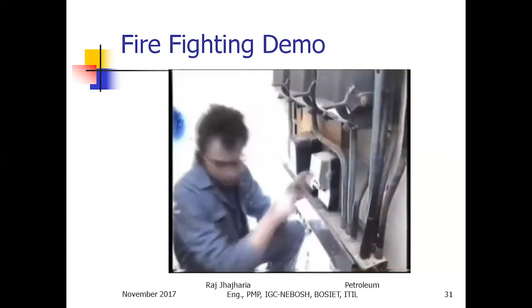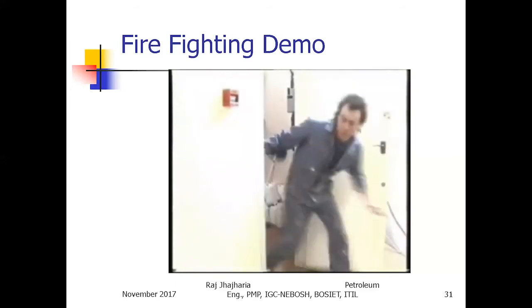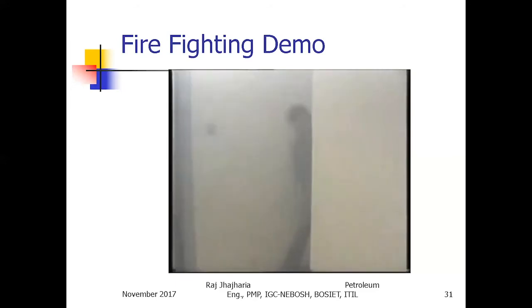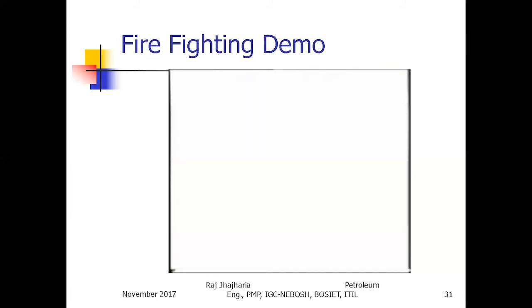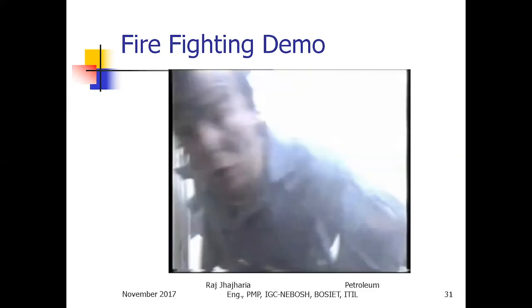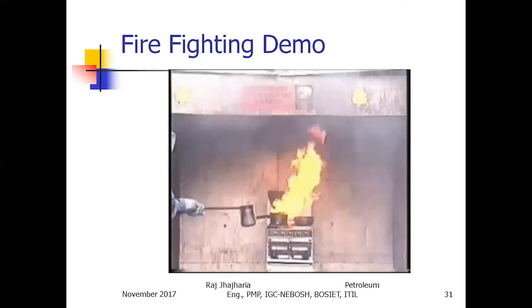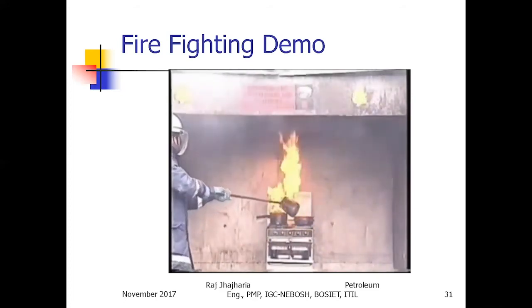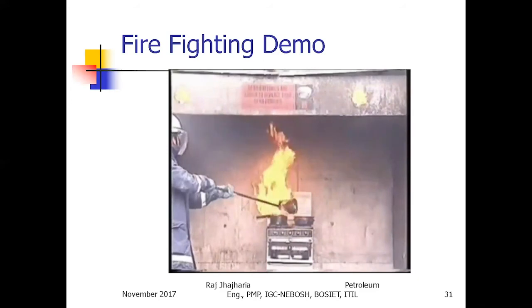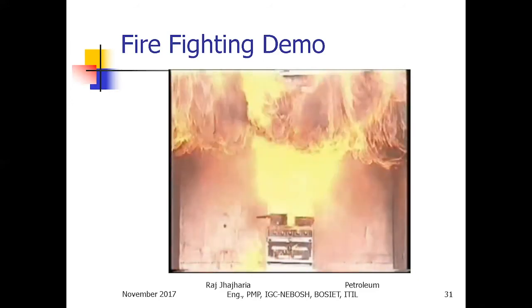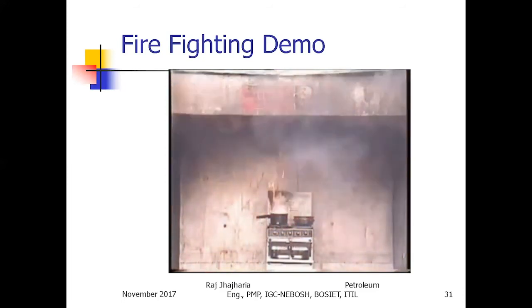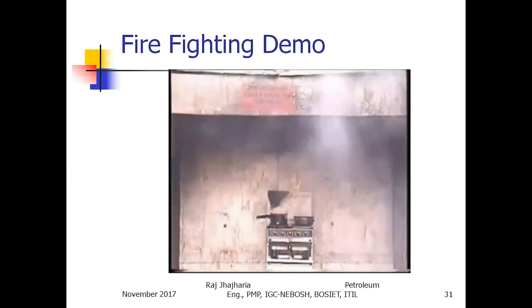There are some fires in which water must never be used, because it'll either make the fire worse or it's potentially lethal. Most people are aware that water and electricity do not mix. The likely outcome of applying water on anything electrical is electrocution. And the reaction you will get by adding just a small amount of water to a flammable liquid fire can be terrifying. Not only will it intensify the fire, but it is also likely to cause the fire to spread and ignite other materials that it comes in contact with.